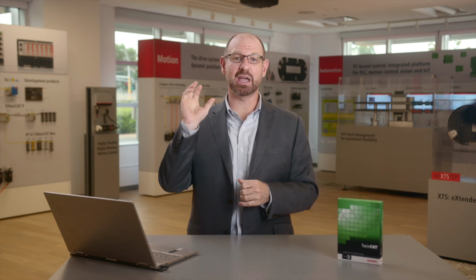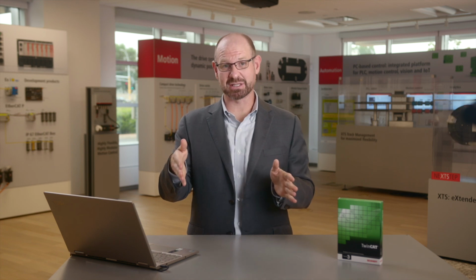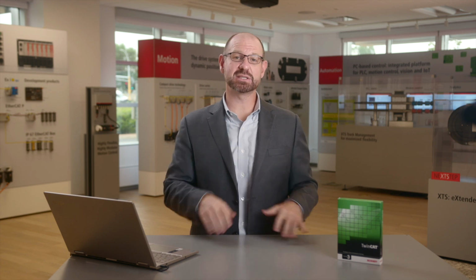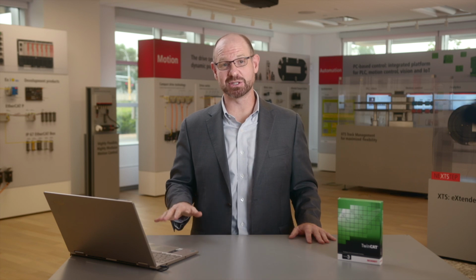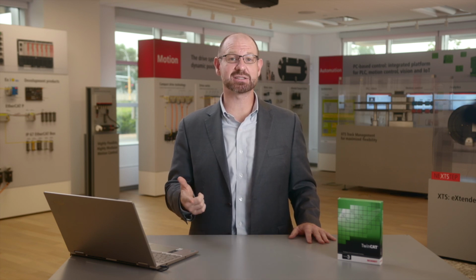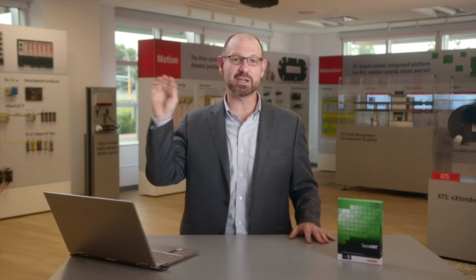So what they did was the ERP system actually figures out the order of the processes, generates what needs to happen in the PLC stepwise, and then makes OPC UA method calls to the PLC that say, here's your first step, go do it. Here's your second step, go do it. Here's your third step, go do it. And then from the ERP system side, if they implement a new model or a new process, a new product, they can insert that new option in the ERP system, dynamically generate the background, and never have to touch the program running in the machines. Never have to go out to the machines and run a new recipe. So it was connectivity, it was lot size 1, it was custom products all the way from e-commerce website all the way to production. It was very innovative, and these are kind of some of the things that we've seen that are interesting in the IoT space.